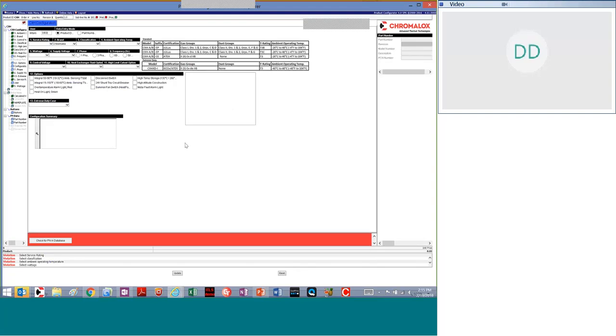So again, all those selections from before. Grade classifications, different T ratings that we can offer. There's that Arctic Duty I spoke about. It's important to remember, if you select the Arctic Duty, that is the -60 rated motor. Last I heard, it's 15 to 16 weeks delivery time. You need to know that. This is a very specific application. You would be going for that, but know it's there, know what it's for.